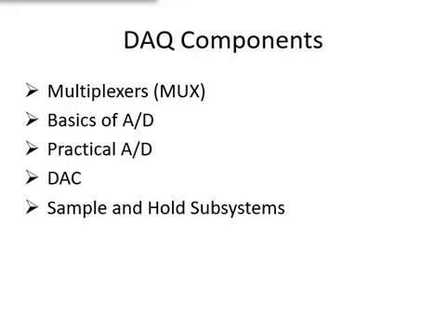If it is necessary to control the experiment or process, the computer must supply output in digital or analog form. If the required control signal is analog, in order to control such components as valves and heaters, the computer system digital output must be processed through a digital to analog converter.